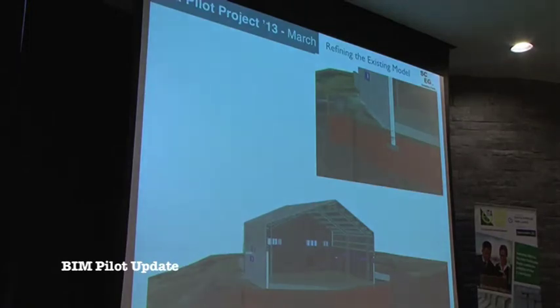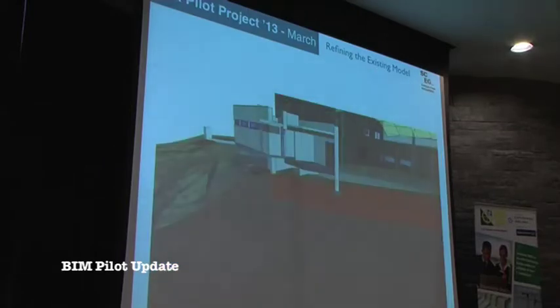So this is an interesting feature of modeling, something I try to do all the time now. When you look at the terrain, you can see this bit here, the block, if you like, came from the point cloud, where this surface here came from the UAV overflight. You can see there's a discrepancy here, but really this point cloud data was given to us as XYZ coordinates. Of course, they couldn't see under the floor in the building, so they've interpolated. And also the model, as I got it from Bernard, just shows the floor, and of course there's a big gap under the floor, which doesn't exist in reality. So we need to make better sense of it.